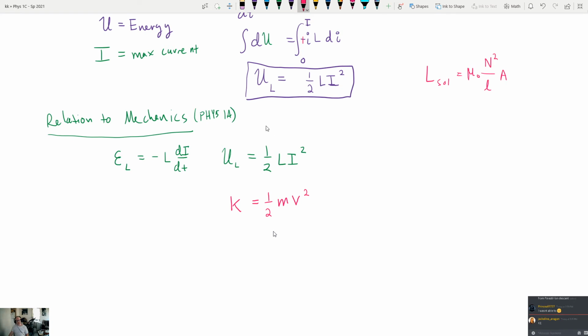So again, you get that. And then you multiply this by the rate at which the electrons move, because that's what I is, right? This quantity tells you effectively how massive your electrons are, and then the current tells you how fast they're moving. When you combine those two things together, you get a type of energy, and we call it the energy of the inductor. But it is a type of kinetic energy. It's energy that's only there because the electrons are moving. If the electrons stop moving, you have no energy in the inductor anymore, right?